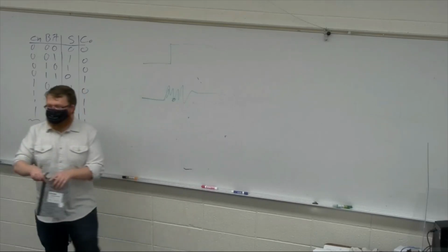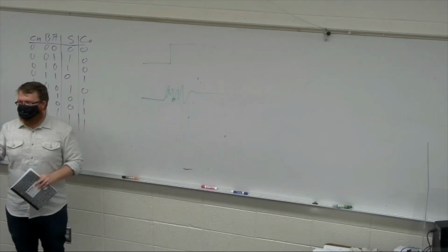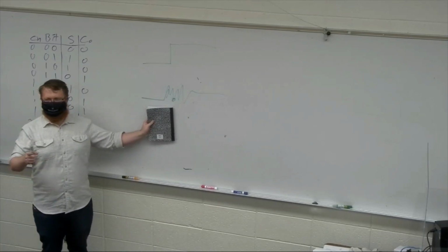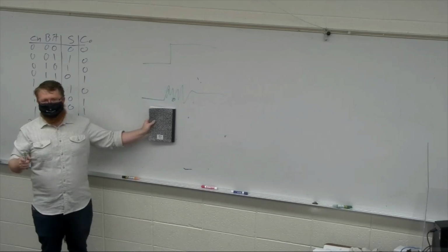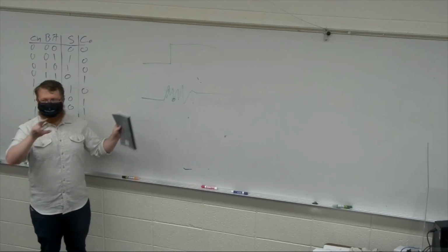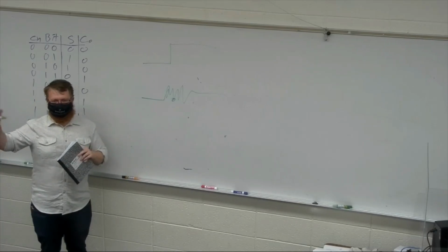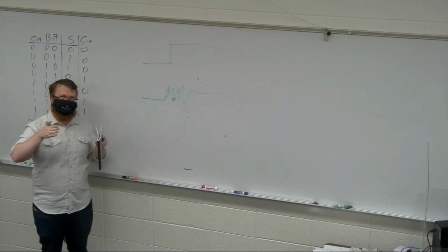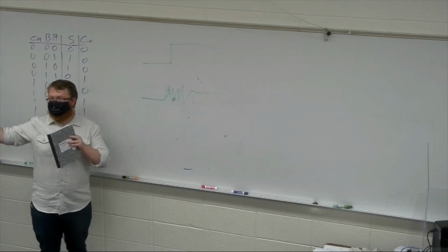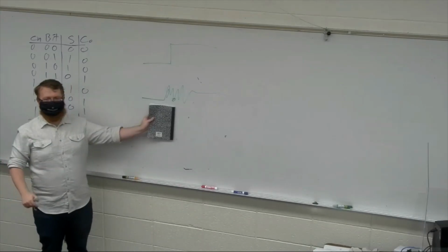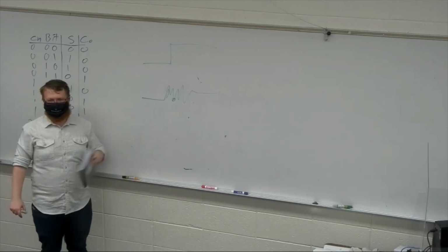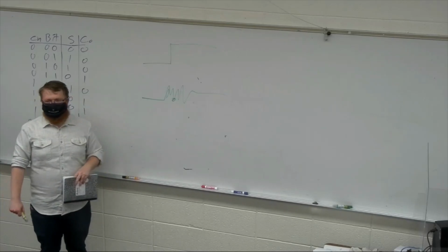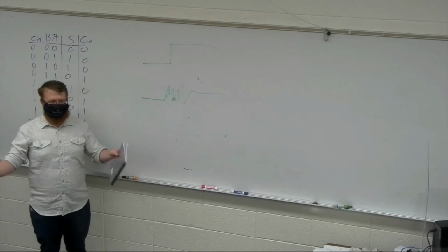That is actually a method that you will see as well, and it's not just one flip-flop, because the first flip-flop can latch in a bad value. The book covers this in more detail. I don't use this one very often, but you can just chain a couple of flip-flops together, sometimes just two, and clocking it in, the chained flip-flops add a level of stability that will make sure that you don't end up swapping back and forth. That's debouncing. It's mostly just an issue to be aware of, and you will run into it at some point.